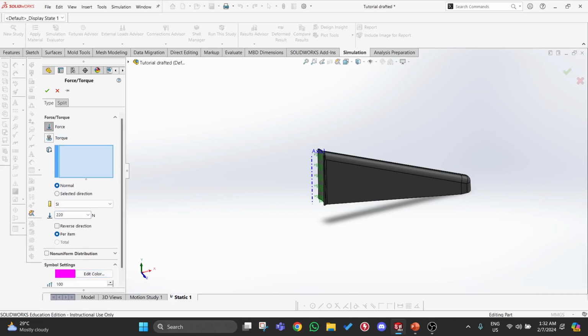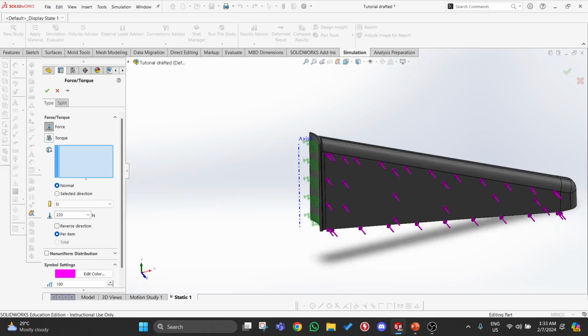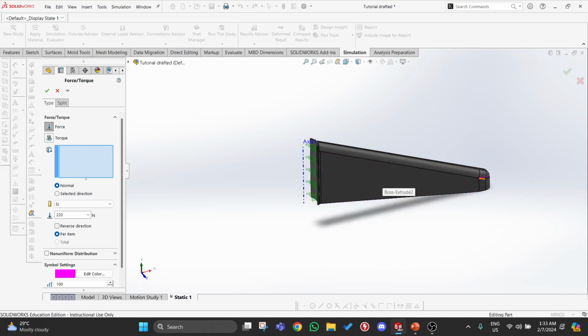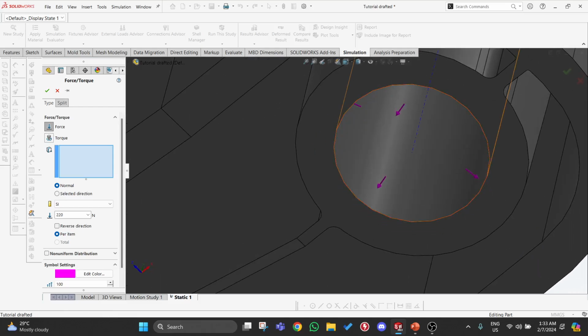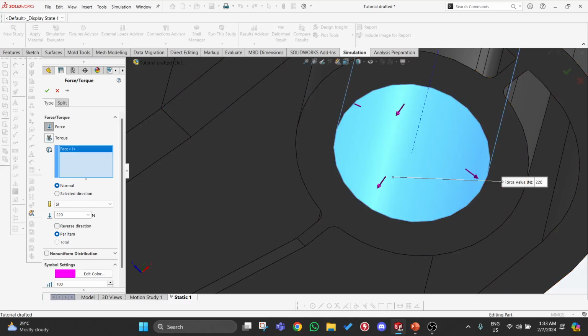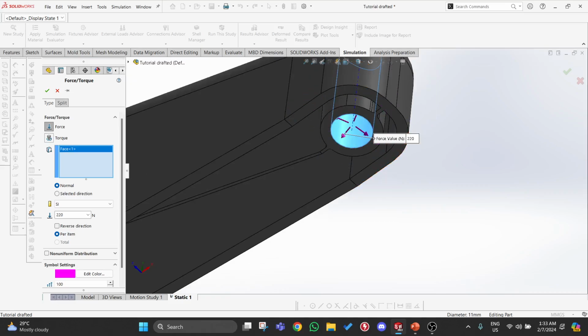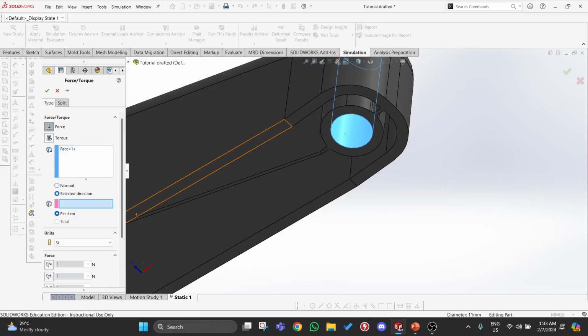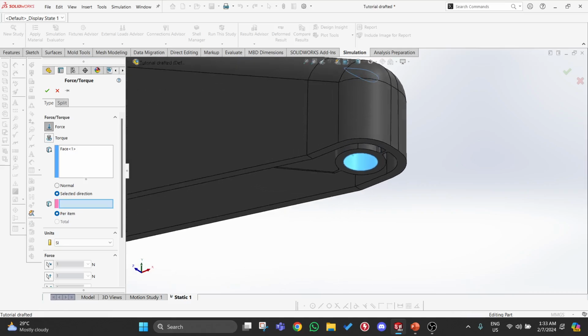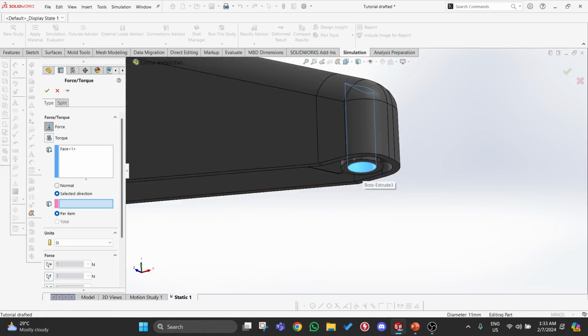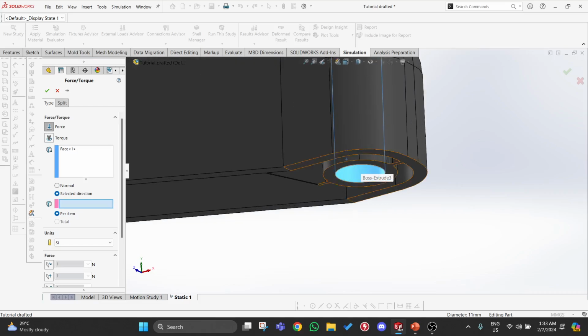And then you want to check your normal. If you click on normal, normal is going to push towards one direction. So if this is put up here, it's going to push outwards, it's going to push here, it's going to push here, right? But your chair doesn't move that way. Your chair goes up, it doesn't move towards the side. So you select a direction. You want to make it move up rather than push towards the side, because your force is not pushing towards anything. It's not moving, it's just pushing upwards, just handling a weight in this scenario at least.